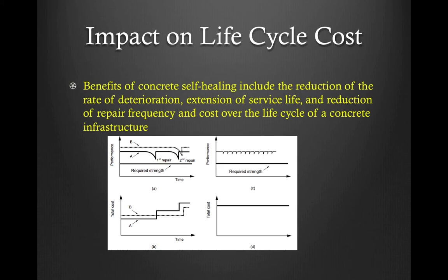Impact on life cycle cost. Benefits of concrete self-healing include the reduction of the rate of deterioration, extension of service life, and the reduction of repair frequency and cost over the life cycle of a concrete infrastructure. As seen in the figure, examples A and B, the conceptual life cycle cost model emphasizes cost increase associated with repair events for conventional concrete structure.